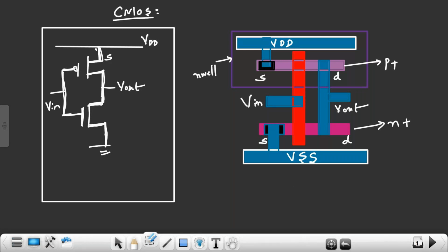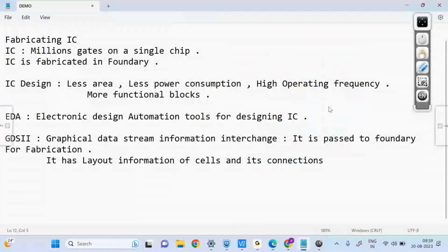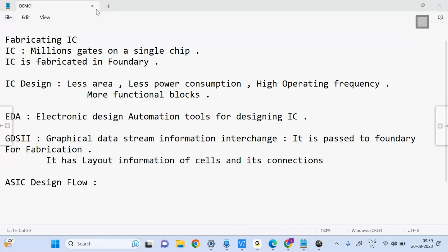To understand the role of physical design engineers, we have to understand this ASIC design flow. What will PD engineers do? We have to understand that. What is the role of PD engineers? From where does our role start? To understand that, we have to understand this ASIC design flow, from synthesis to GDSII format. Yes, correct. Our role starts from synthesis.